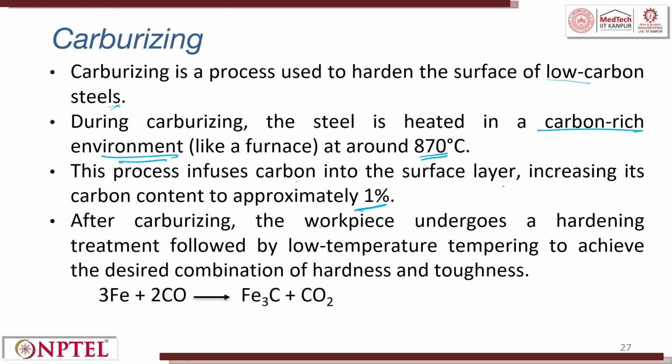After carburizing, the workpiece undergoes a hardening treatment followed by low temperature tempering to achieve the desired combination of toughness and hardness. So, after you do case hardening, carburizing, you do a low temperature tempering also. 3Fe plus 2CO leads to Fe3C plus CO2.